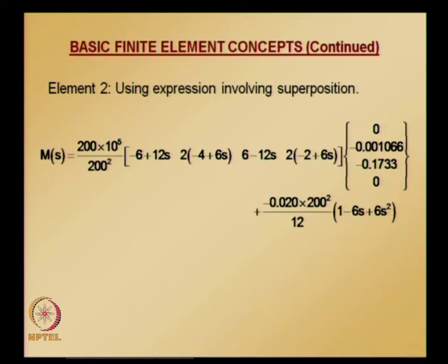Element 2: the first part is interpolation using finite element shape functions, and the second part comes from fixed end moment correction. This fixed end moment expression corresponds to a fixed end beam subjected to distributed load.